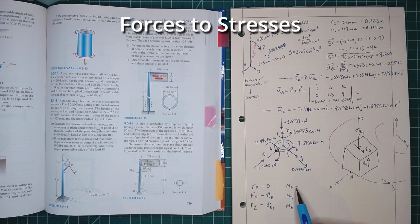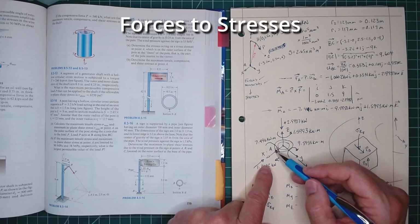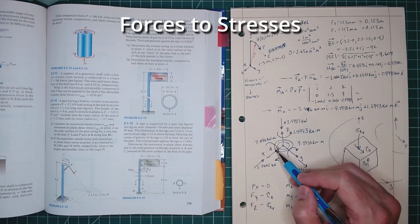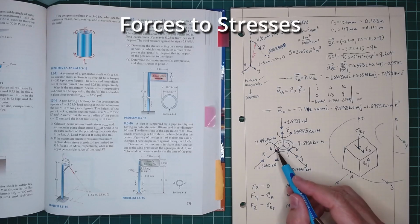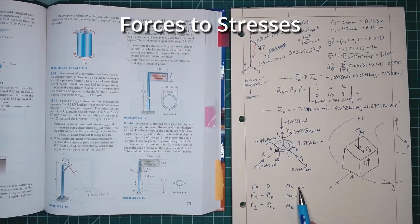Let's take a look at our moment in the X. This is bending about the X-axis, so we're rotating this section about the X-axis. Again, if we look at the bending about the X-axis, A is on the neutral axis. In bending, if our point A is on our neutral axis, there is 0 bending stress or axial stress associated with that. And in this case, there's no shear stress associated with that rotation or bending either. So moment in X provides no stress here.